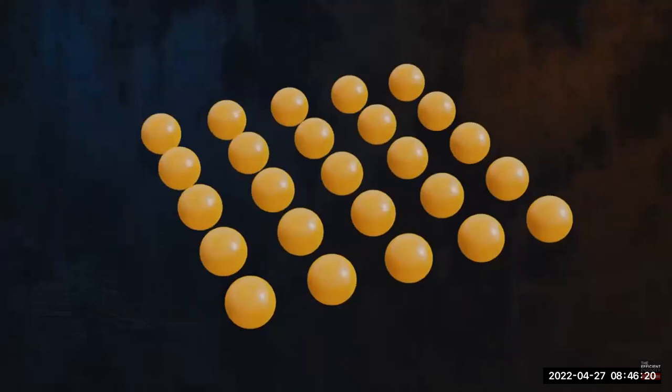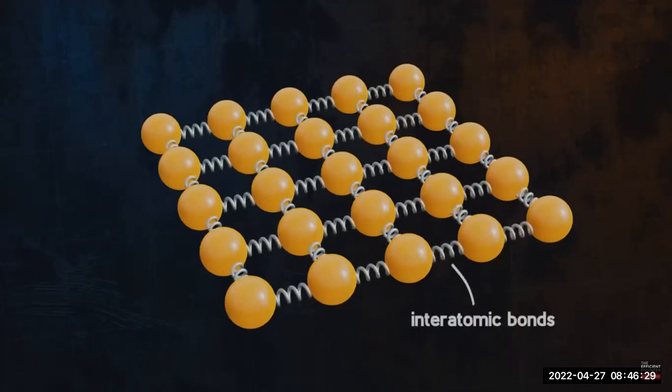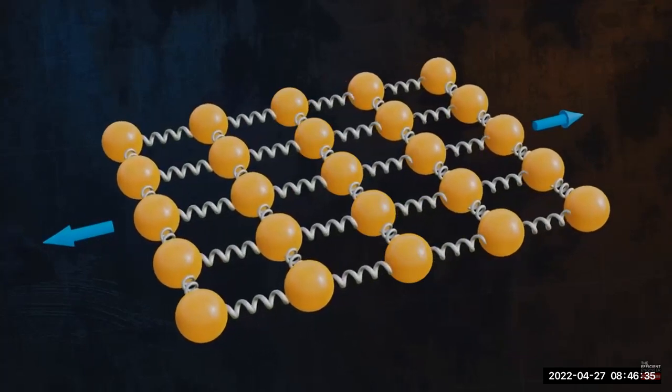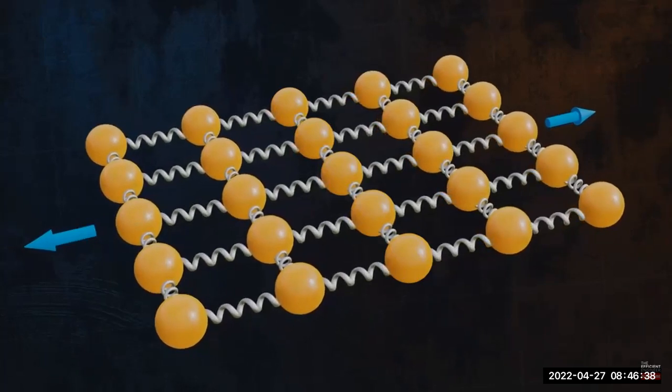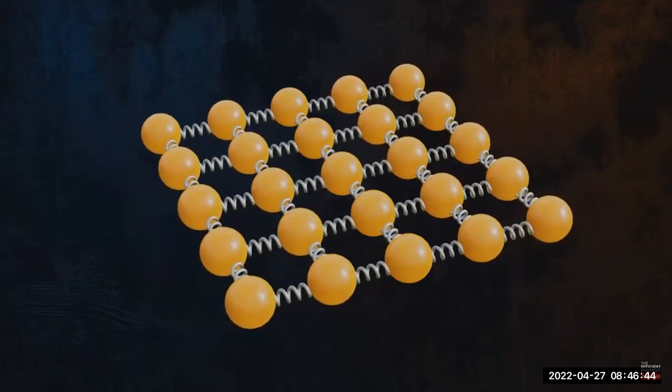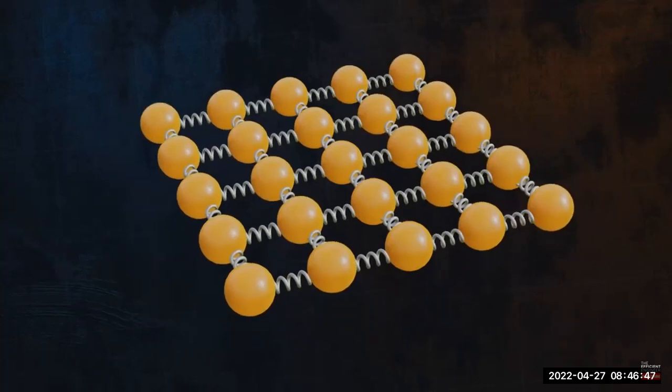Understanding what is happening at the atomic level can give us a better understanding of Young's modulus. On an atomic level, a material's Young's modulus is closely related to the strength of the bonds between its atoms. We can imagine these interatomic bonds as tiny springs connecting adjacent atoms. Elastic strain is the result of an increase in spacing between the atoms of the material and is resisted by the strength of the interatomic bonds, or the stiffness of the little springs in our model. This is very different to the mechanism behind plastic deformation, which involves rearrangement of the position of the atoms.